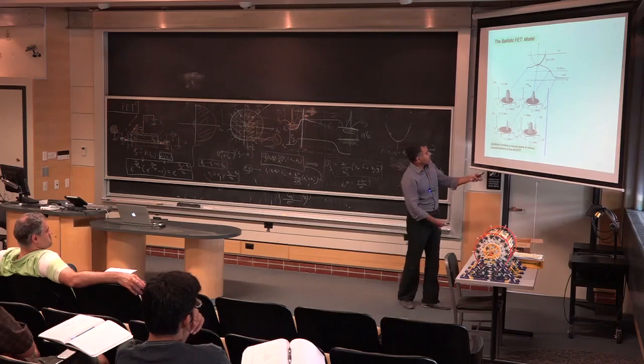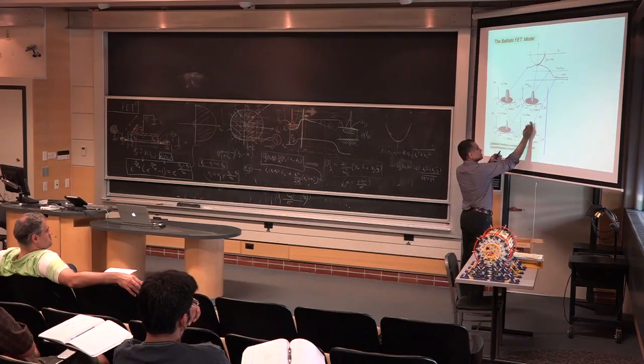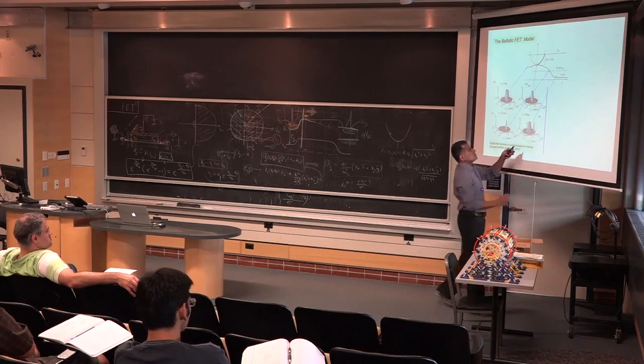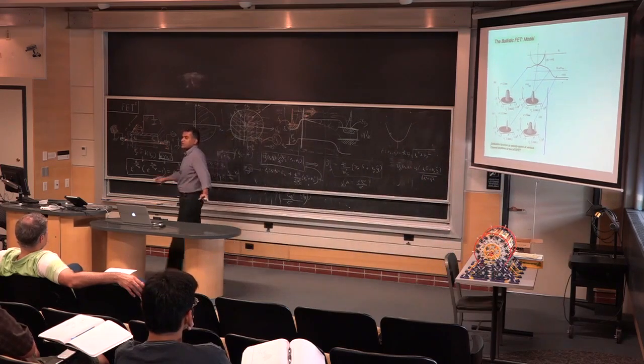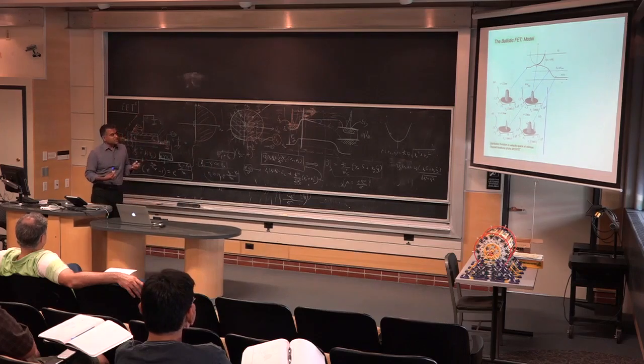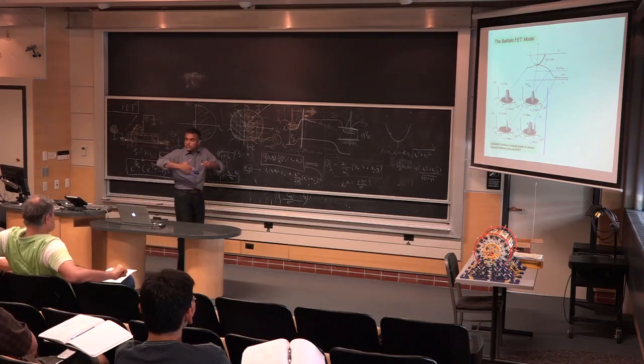And then when you reach the drain, you have still those very fast moving electrons, but you also have this whole sea of other left and right going carriers. So they kind of merge, and then it dumps all the heat up there. And so when people measure these devices, the drain is hotter. You can measure it. The temperature is hotter because the electron just dumped all its energy into the drain contact, not in the channel anymore. If you have a very long channel, then you have Joule heating.